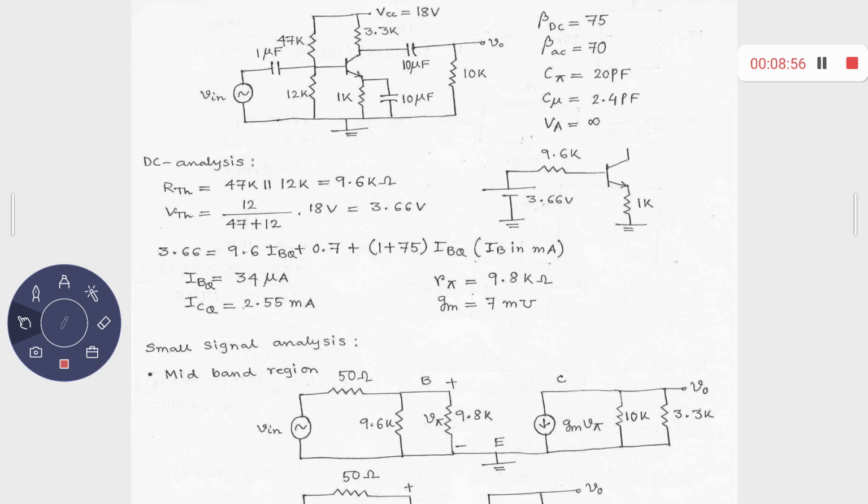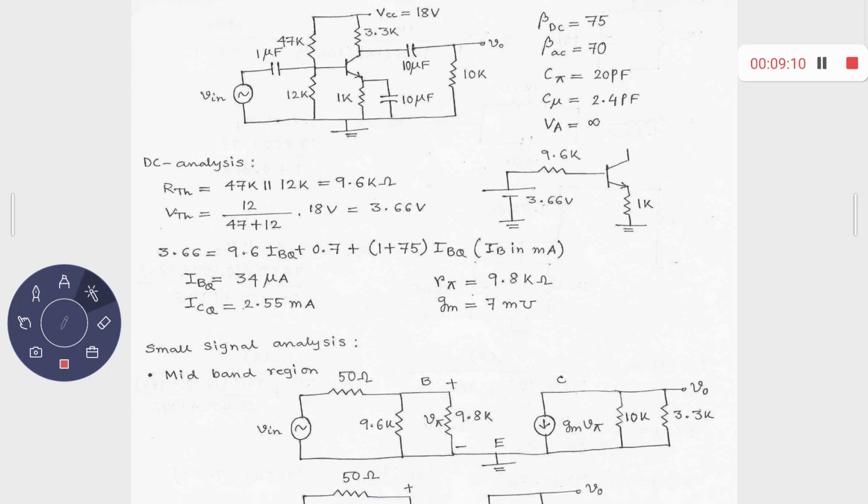So actually it will provide you some impedance. But when it is in parallel with the 10 microfarad, at a signal frequency of 100 kilohertz or so, this 10 microfarad is acting as a short circuited path, right? So this is actually a short circuit, because the 1 microfarad and 10 microfarad are both short circuited paths. Once again, obviously, apart from that, you have some internal capacitance, if you can remember.